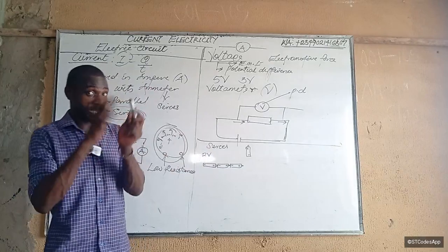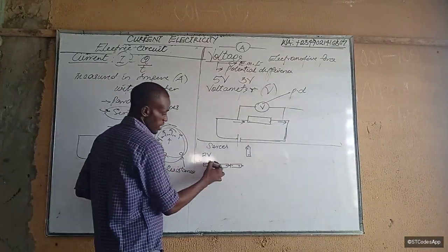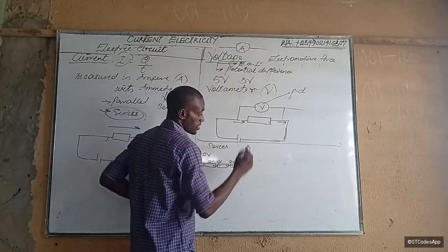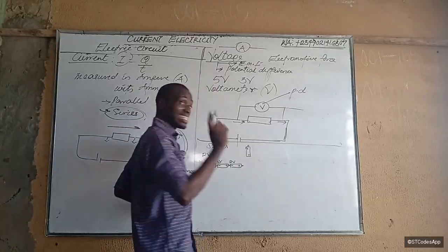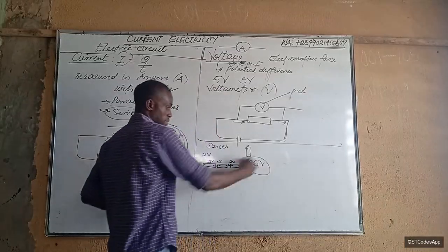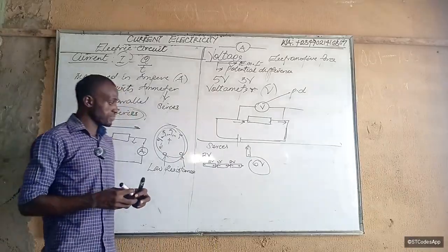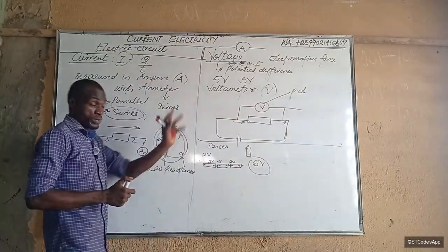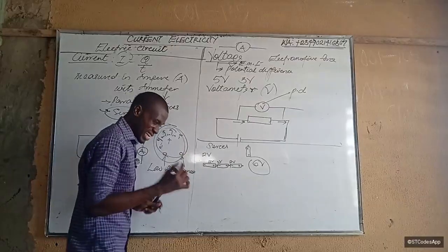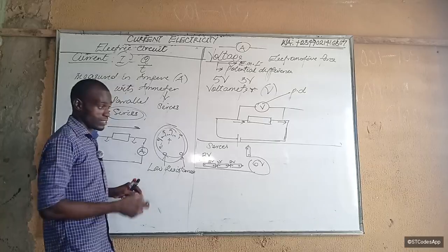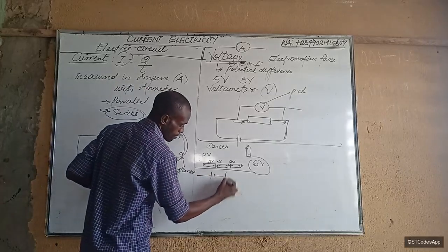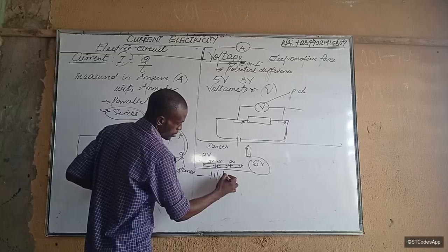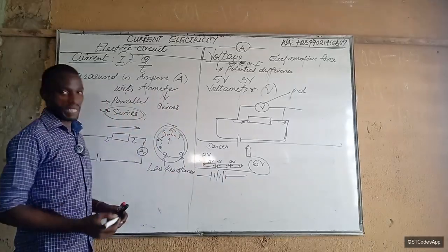If all of them are 2 volts, 2 volts, 2 volts, the total EMF that will be delivered in an ideal case is 6 volts. Keep in mind the word ideal; I'll soon talk about that. So in series, 2 volts, 2 volts, 2 volts, we get 6 volts. The way we draw that in a circuit diagram is we won't draw every battery, we'll basically draw it like this. There are three 2-volt cells here, that's 6 volts.